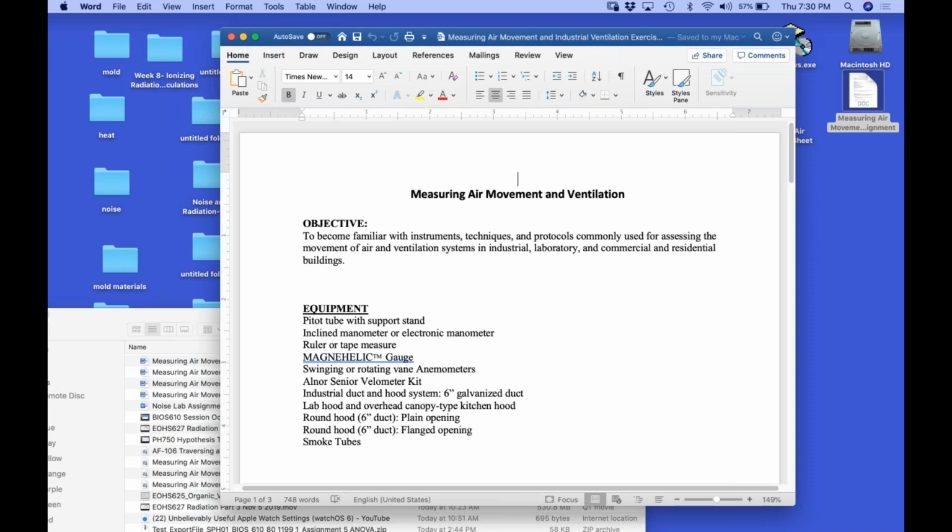Let's figure out what the volume is right here. I'll wait for you guys to catch up. So it's 1,848. I'm going to call it 1,800 to make it simple. 1,800 feet per minute. What's the cross-sectional area of a 6-inch duct? Pi r squared, but you have to change it into feet.